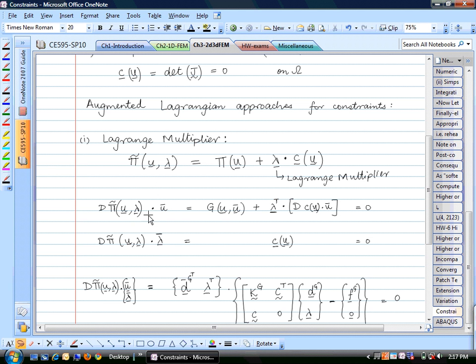When you minimize this with respect to u, that gives you the old virtual work, whatever you had before. And the only thing that you need to find new derivatives for is this constraint. So you get a new equation that looks something like this. Your Kd minus f is sitting in here, and this term is going to lead to an additional sort of force on your system.